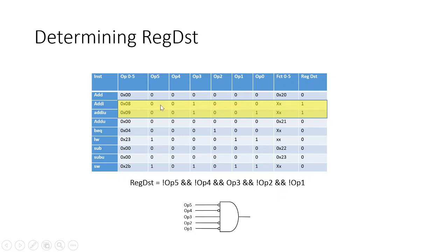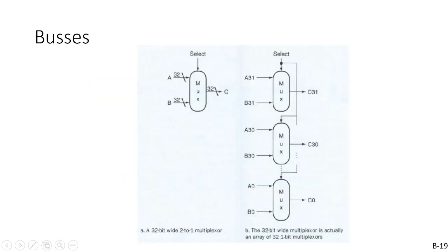So this is just to demonstrate the so what factor. Here's where all of this comes into play. You can see MIPS was designed with opcodes and the function code to go through its logic, and they designed it just the way we've been talking about. This is the simplified circuit and design here with the inversions on op5, 4, 2, and 1. Just some symbology I didn't talk about last time. Basically, when you see the slash, that represents a bus. This is the compressed version, because it's a lot more work to write out a 32-bit wide multiplexer, for example, every bit and its carry. So we simplify it with this picture.